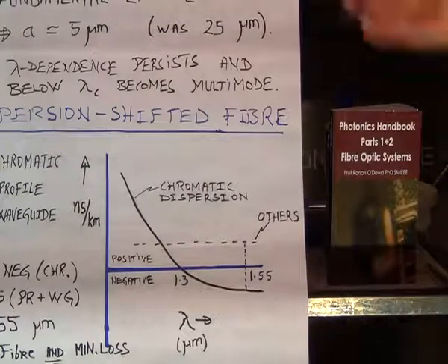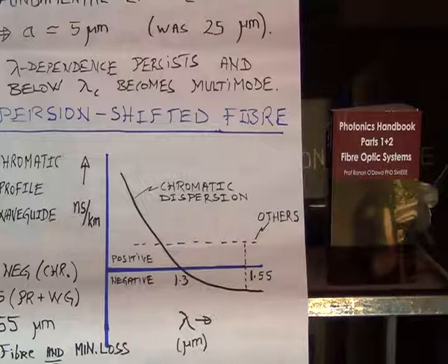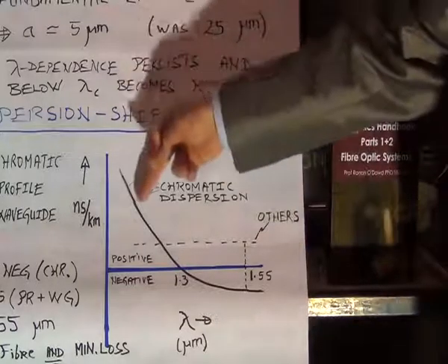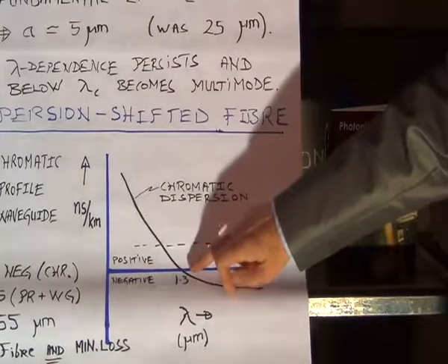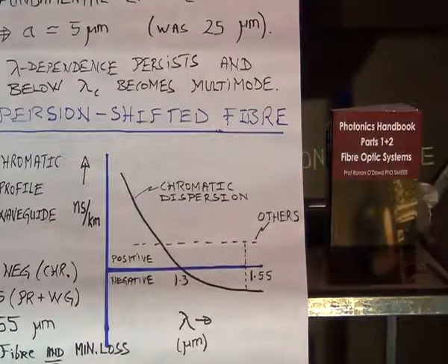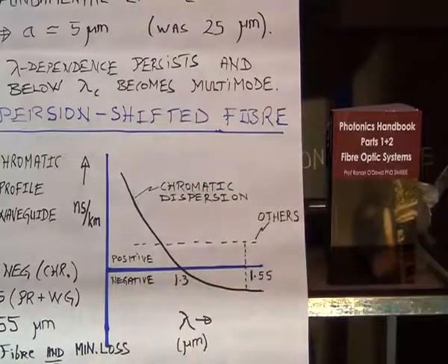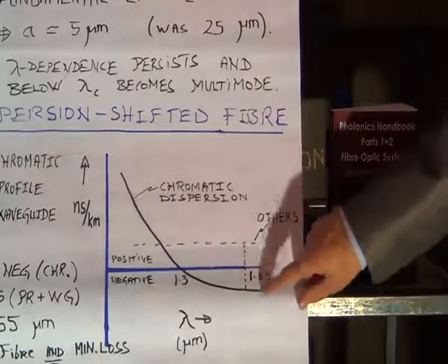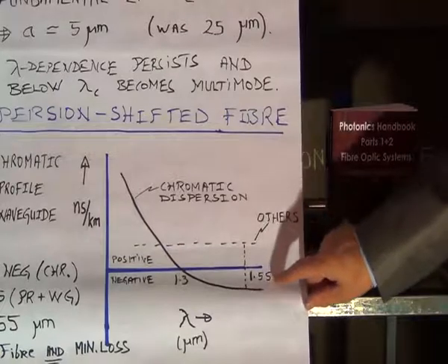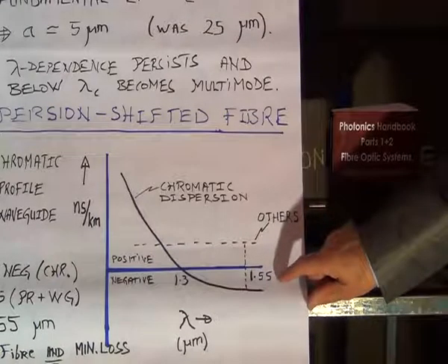And then they got on and they did everything we've just calculated about the multimode dispersion. Okay? So chromatic dispersion goes through naught for SiO2 at that wavelength. And then it goes negative. And it's negative out at our new wavelength 1.55 microns, our 1980s and 90s lasers.